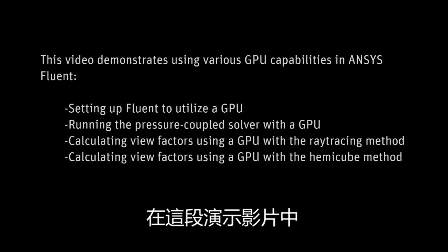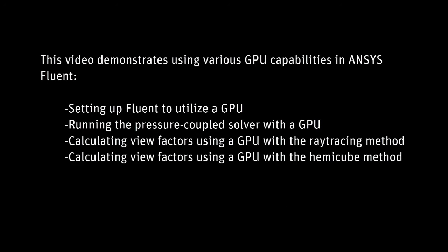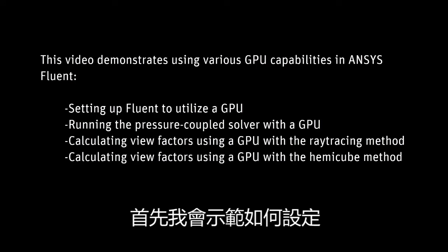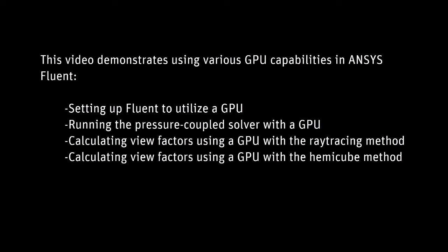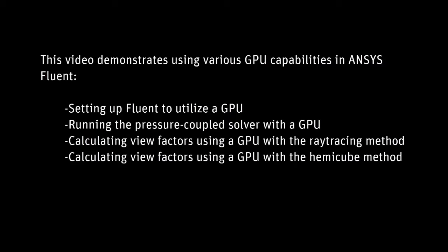In this demonstration, you'll learn about the various GPU capabilities in ANSYS Fluent. The main benefit of using a GPU is that for some cases it can speed up calculation times. First, I will show you how to set up Fluent to utilize a GPU, and then I'll walk through some TUI commands to use a GPU for various calculations.